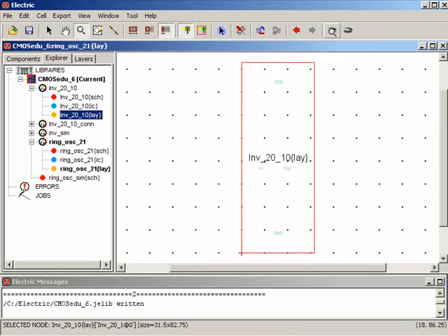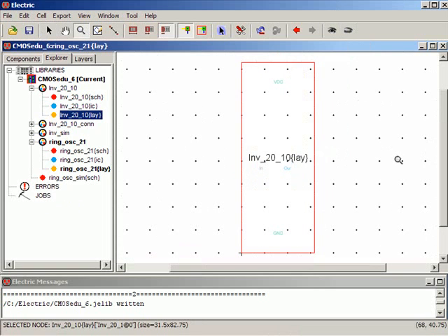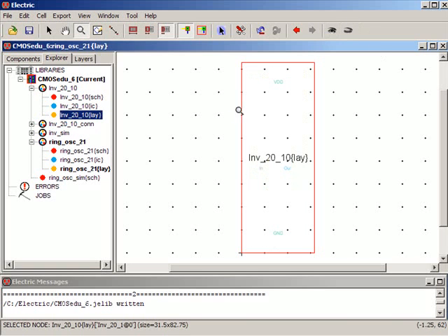If I want to see inside the cell, I don't use Control down or Control U. I view the contents of the cell. I'm not going to use that for the moment. I'm going to make my layout as quickly as possible, and then I'll make comments about making it nicer later. Now note, on all of my ports, the inputs and outputs are all on metal 1. So I'll leave that closed.